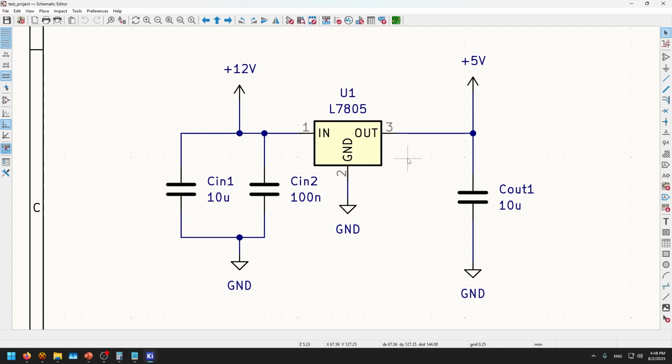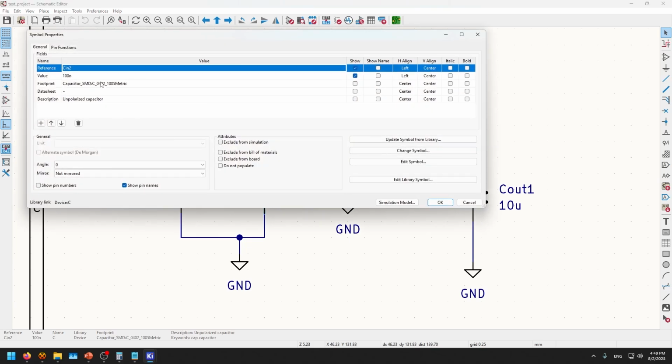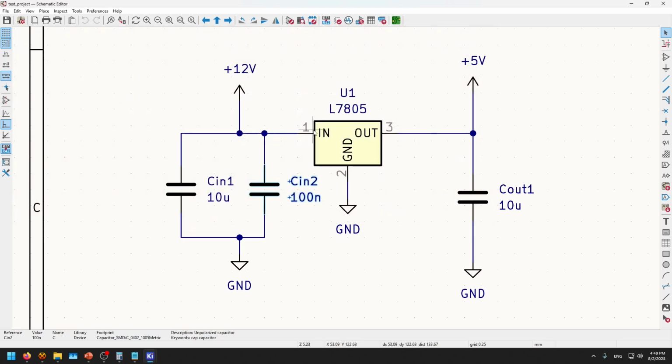It tells you that you can use it without output capacitors, but the best practice is to use an output capacitor. And I also recommend putting a small-size input capacitor, like 0402 and 100 nanofarads, very, very close to the input pin, as we will see right in here.